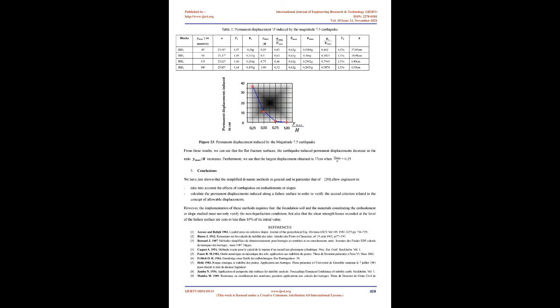Where T_i is the eigenperiod associated with mode i. Using formulas 60 and 61, the peak acceleration of the dam is found to be equal to 0.62. And the equivalent distortion obtained, equal to 0.060%, is very little different from its initial value, 0.065%. Using the charts of 20, average values, or the relations proposed by 19, we obtain the values of the induced permanent displacements D at different rupture lines, which are given in Table 2 and Figure 23.